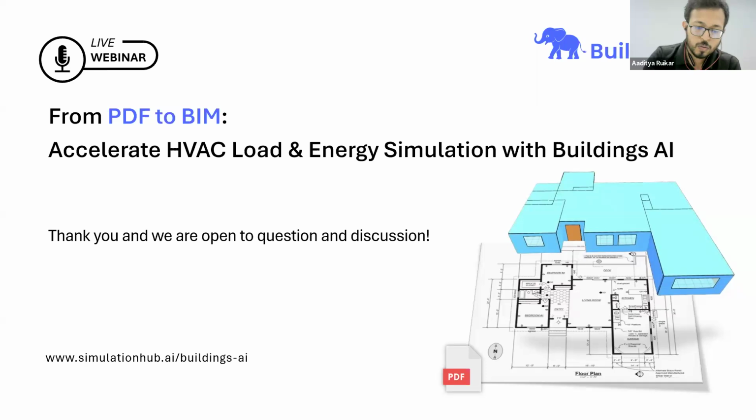Yeah, I'll go with this. Basically, you have to provide accurate internal wall thickness so that those gaps will get avoided. But if gaps still arise, you are exporting into FloorSpaceJS anyway. You can go into FloorSpaceJS, edit those, fill those gaps, and then import that into the built-in configuration to get an error-free Revit file.